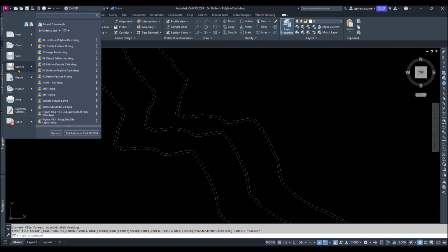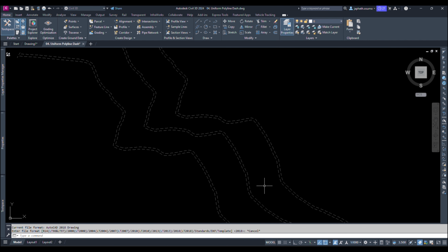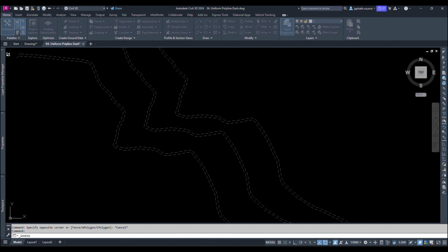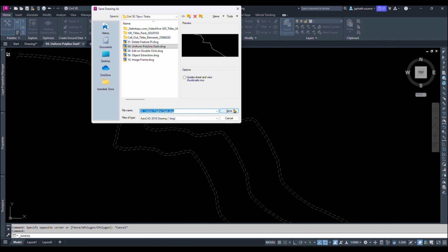When FILEDIA is set to 0 in Civil 3D, dialog boxes are not displayed. You can still request a file dialog box to appear by entering a tilde in response to the command prompt. With FILEDIA set to 1, dialog boxes are displayed. However, if a script is active, an ordinary prompt is displayed. Prompts are also displayed if an AutoLISP or ObjectARX program is active.